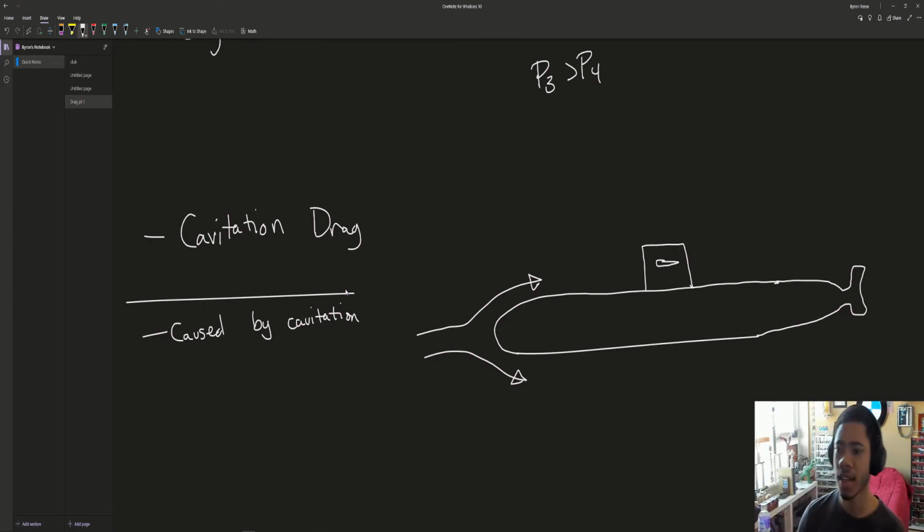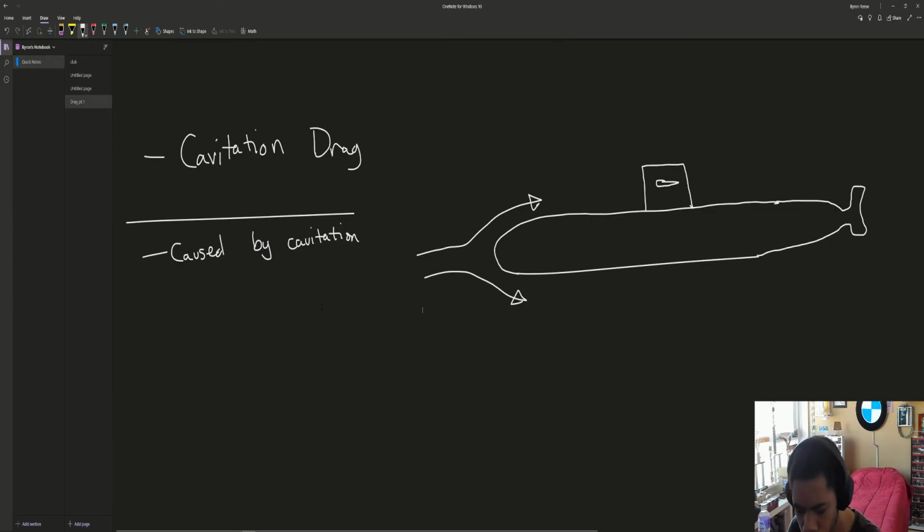And what happens is that once it turns into vapor, it has different properties. So it turns into this vapor bubble. But then the pressure drops back down, and what happens is that it wants to turn back into water. So you essentially get these microbursts of exploding bubbles.